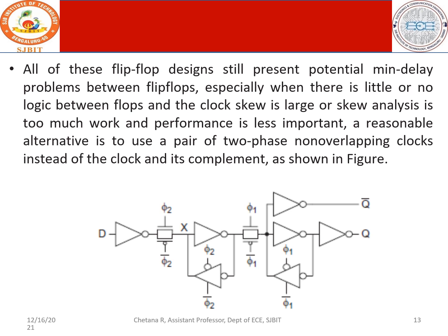So next we have the flip-flop designs which still present potential minimum delay problems. All these flip-flop designs still present potential minimum delay problems between flip-flops, especially when there is little or no logic between flops and clock skew is large or skew analysis is too much work and performance is less important. A reasonable alternative is to use a pair of non-overlapping two-phase clocks instead of clock and its complement.